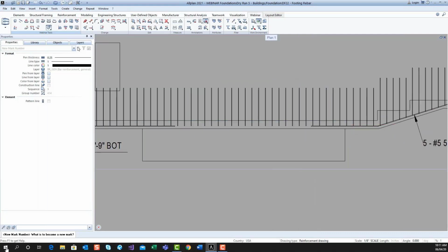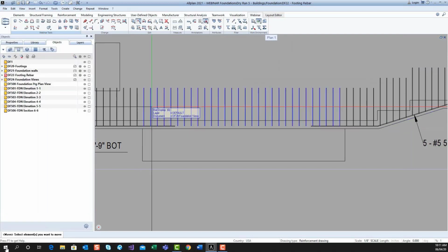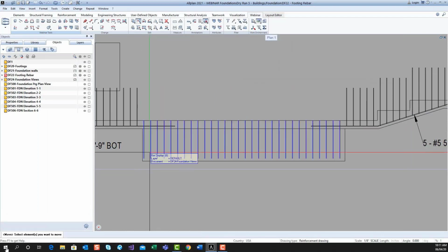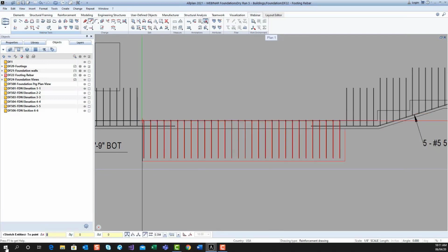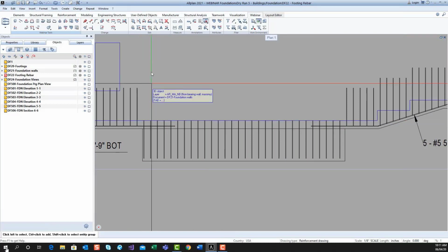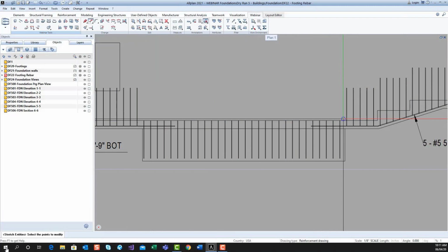And what I'm going to do is, I know these need to be longer. I can do a simple stretch tool from the bottom, but sometimes I catch certain bars I don't want. I'm telling you one way; the other way is doing it differently. What I'm doing here is I'm moving the bar down to its new location. Cover is the same from the bottom, and then I'm going to stretch. Now the first attempt at this, I caught the footing by accident, so I'm going to do the stretch command one more time here and make sure I don't catch that again. Just knowing where to pick is sometimes a benefit.